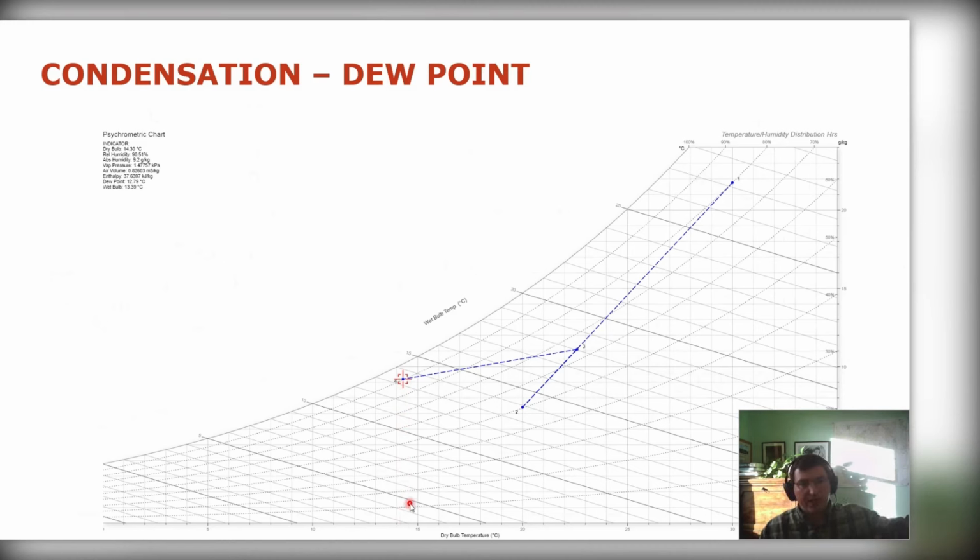So if you came and you put your hand to the air supply, you'd say, oh, it's much colder. Yeah, that's great. That's just cooling us down on this hot day. But what's also happening, it's adding more moisture into the room. And then, well, various things can happen, but quite often that moisture spreads around and starts to condense on the cooler surfaces. That could be the surfaces of the HVAC itself and so on.